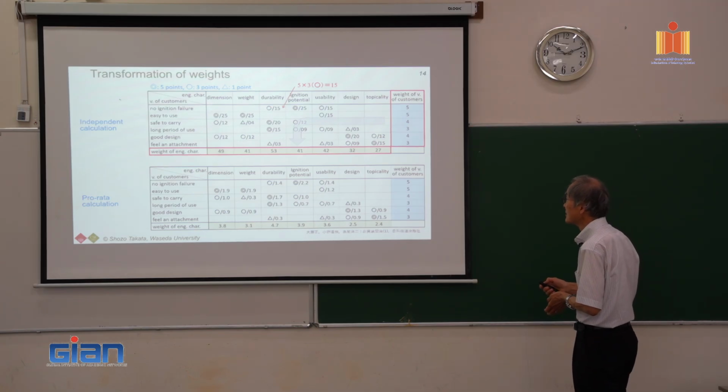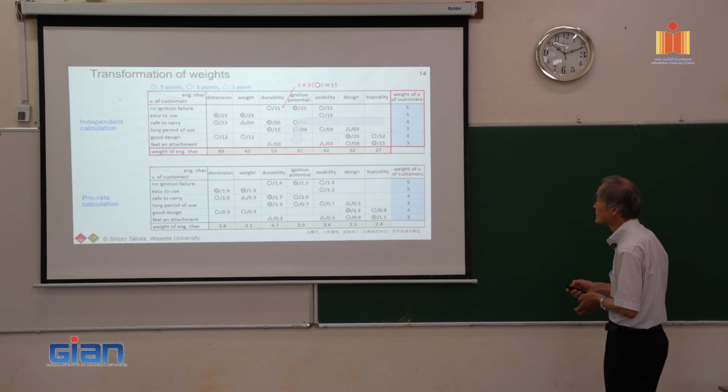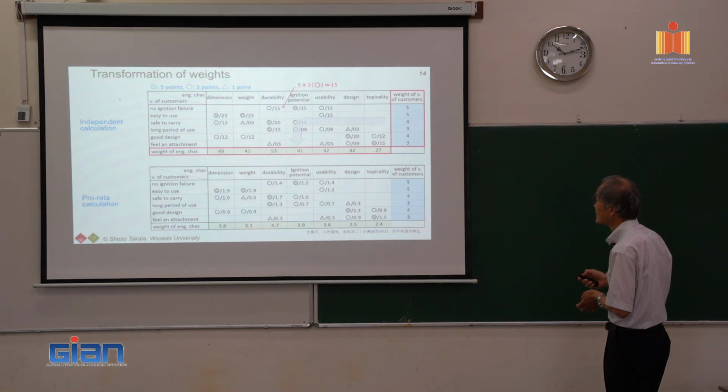And then this voice of customer is related to the durability with the point of 3. And the weight of the importance of this voice of customer is quite high, 5 points. And then 3 multiplied by 5 makes 15.